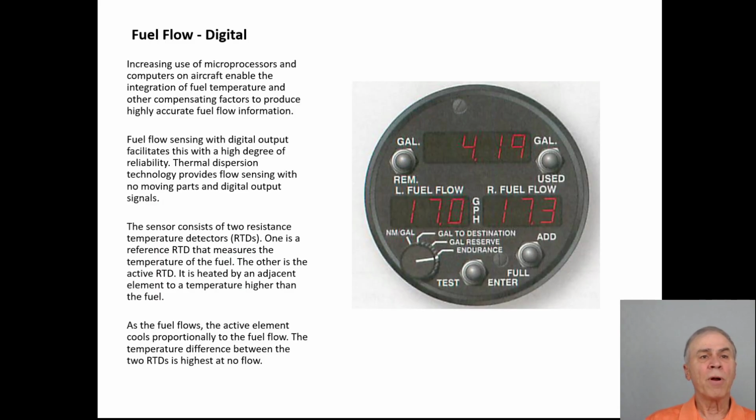Increasing use of microprocessors and computers on aircraft enable the integration of fuel temperature and other compensating factors to produce highly accurate fuel flow information. Fuel flow sensing with digital output facilitates this with a high degree of reliability. Thermal dispersion technology provides fuel sensing with no moving parts and digital output signals.